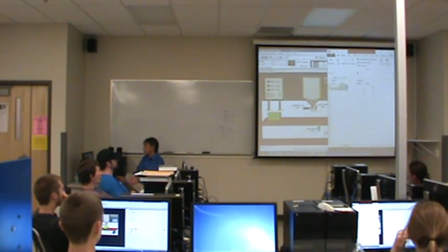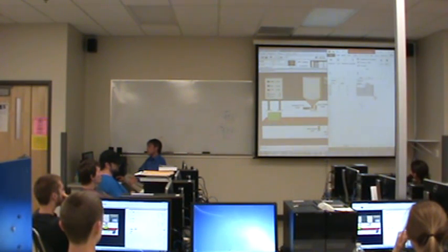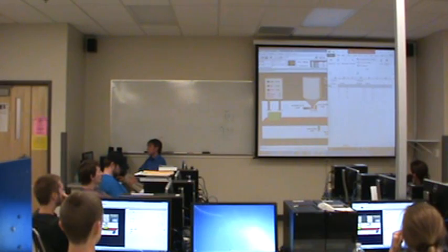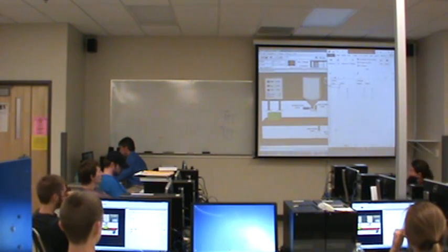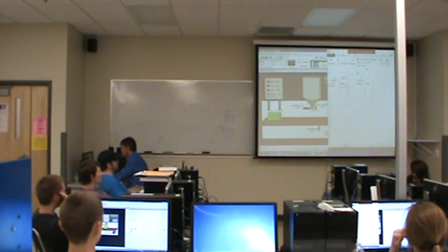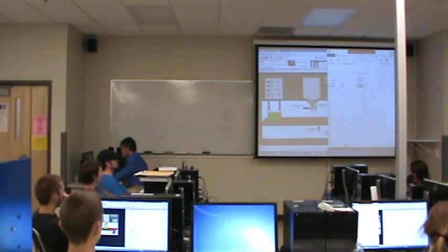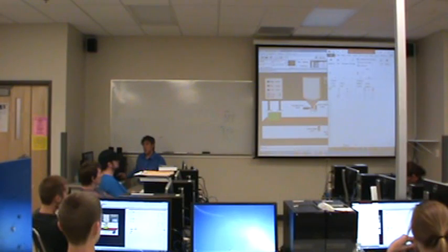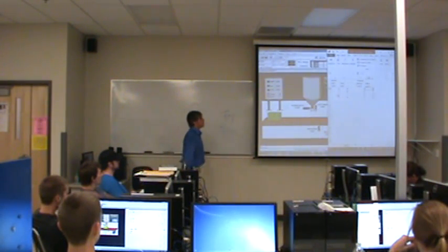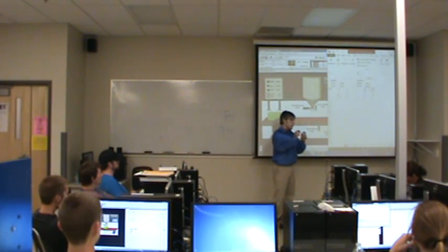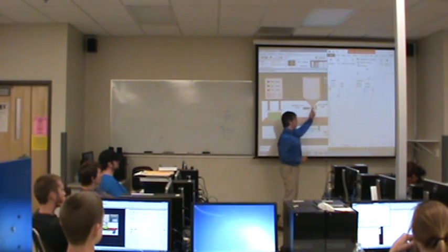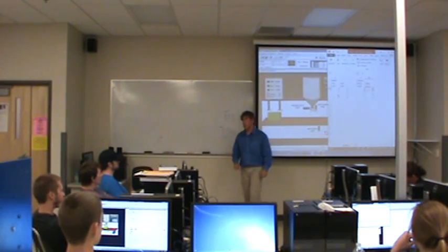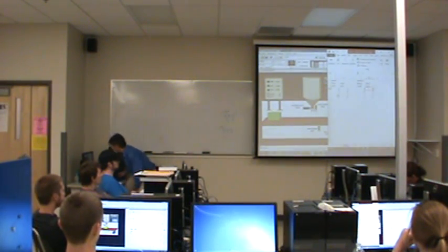Notice all I've done here is create an input list and a response output list. But we have to be a little careful here. Another thing I like to do is put in the addresses. Prox is on input 1/3. Level is on input 1/4. Motor is on output 2/0. And valve is on output 2/1. Okay? We have to be careful. One thing I didn't stress when I was describing the sequence instructions is that your patterns in memory, the bit locations, have to match the bit locations of the inputs and outputs that you want to deal with. Okay? So, let's make that happen.